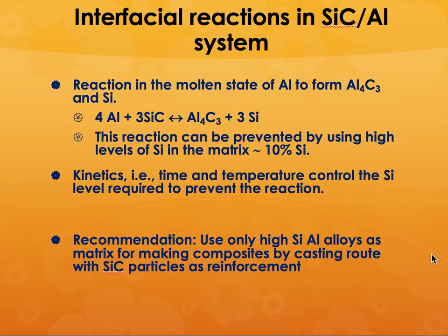Okay, now you can see that, say for example, if you had silicon carbide whiskers in an aluminum matrix, and the application is for making wear resistant aluminum pistons, which used to be used for the Honda sports cars, but I think it is being used for many of the newer cars more recently.